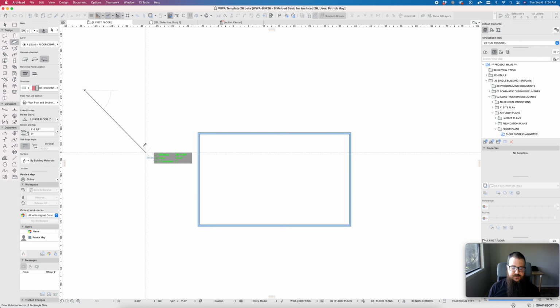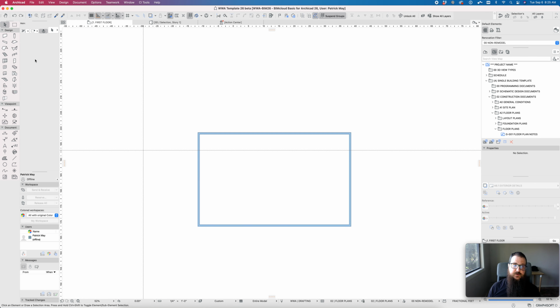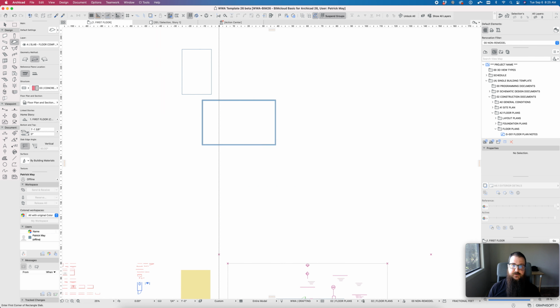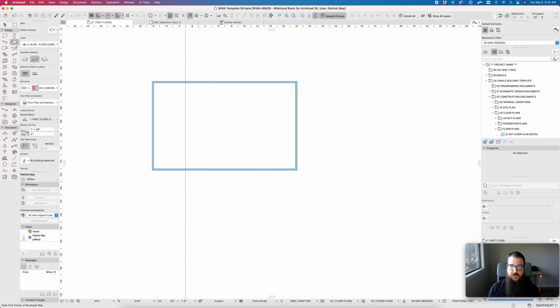And with any of these, you can use the tracker palette right here. And again, Shift R is to lock to a radius, or lock to an angle rather, and then input a radial distance, so 25, for example. With the square rectangular method, you can actually direct input X and Y coordinates. So if you know that your slab is X 20 feet and Y 30 feet, you can input that directly into the slab settings.